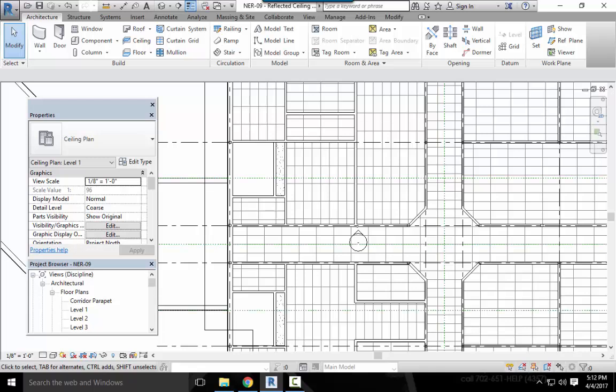Modifying ceiling grids. To be honest, a ceiling consists of nothing more than a basic hatch pattern applied to a material. Actually, everything in Revit is a basic hatch pattern applied to a material. The one unique thing about hatch patterns in Revit is that you can modify them on screen. That means you can move and rotate a hatch pattern. It also means you can move and rotate a grid pattern. Item 1, press escape or modify to cancel the command you're in. We've already done that. Item 2, pick a ceiling grid line as shown in figure 9.6.